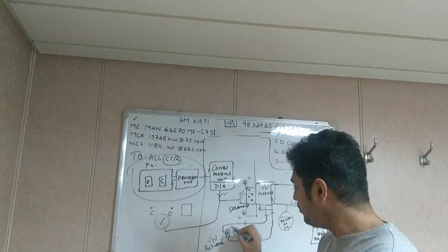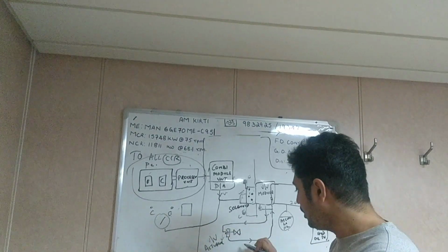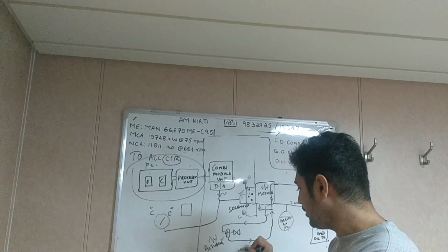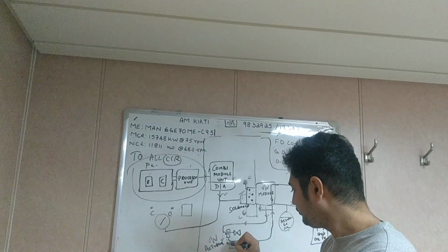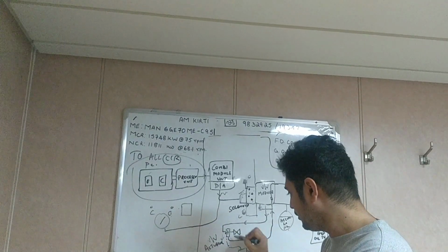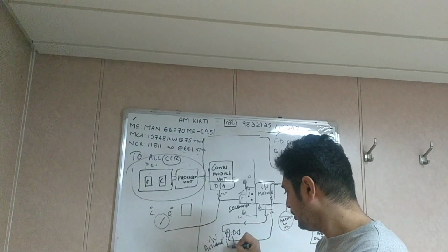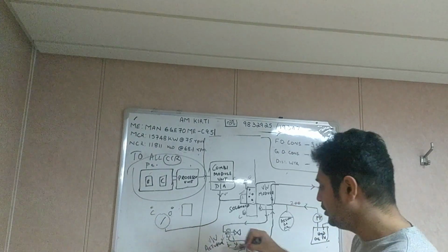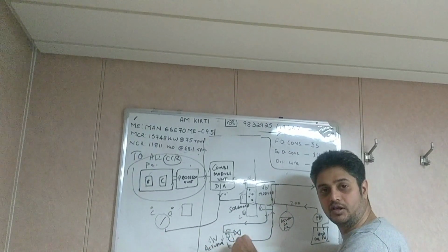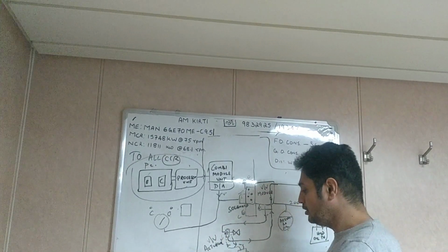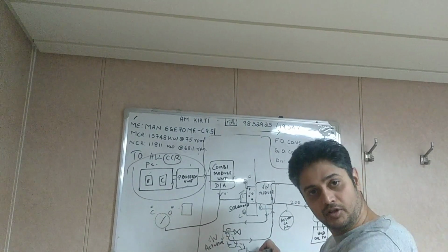local operation. This is remote, no? So for local operation you will have one hand pump. Use this hand pump. You will have a connection here. I'm just drawing in a rough way. This is the inlet and this is the return. Okay, and see whether the valve is turning freely. The valve has to turn freely using the hand pump. This is also a hydraulic pump.